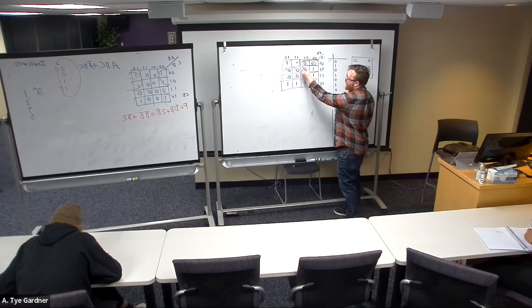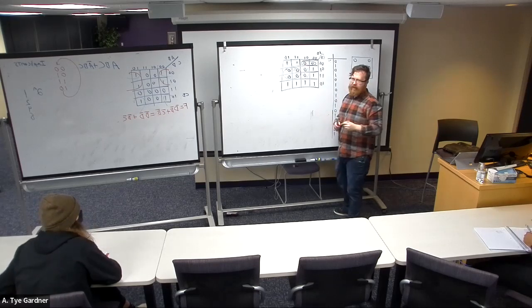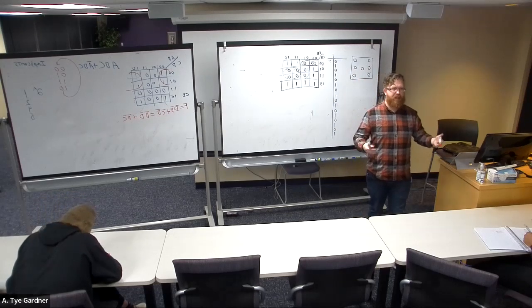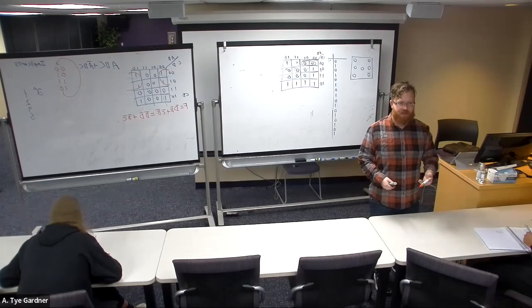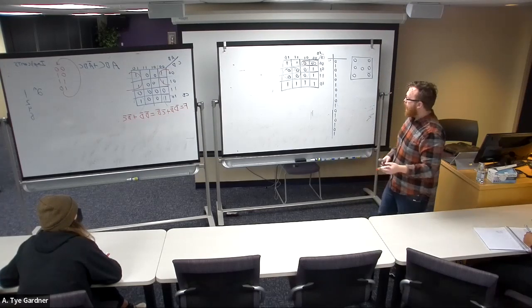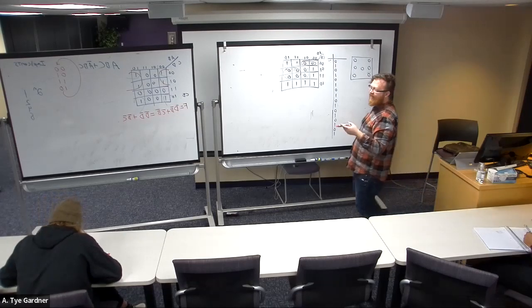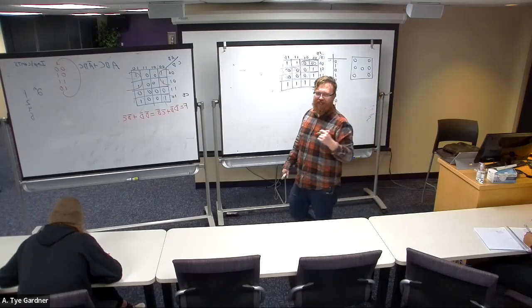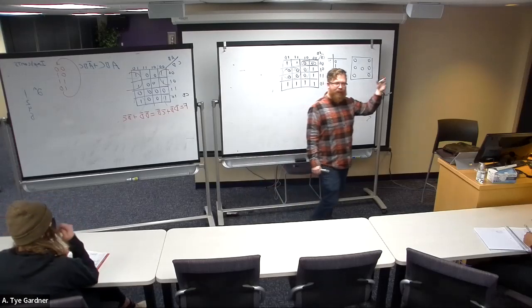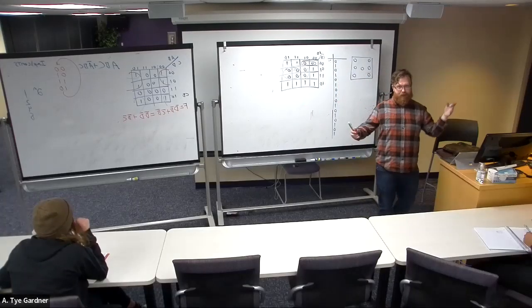For now, don't circle that dashed one. That would be an extra implicant. I don't need it to complete coverage. It's not necessary. But next time, we're going to come back around to this and we will add that, because sometimes the minimum circuit causes problems, it turns out.